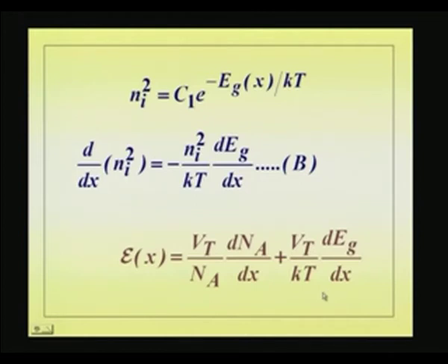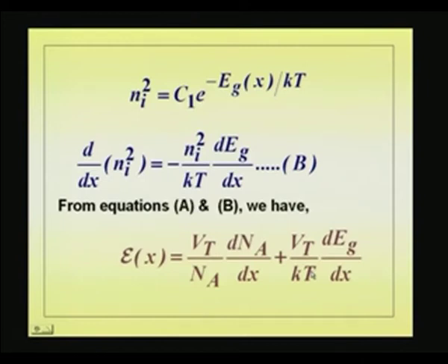It tells you totally now that the electric field is decided by doping gradation plus gradation in the mole fraction, that is gradation in the band gap. Okay. Now, let us take a look at that. So, this is the formula that we have got now, which tells us what is the electric field at thermal equilibrium. Now, when you forward bias the emitter base junction and inject carriers, electrons, that electron experiences this built-in field.